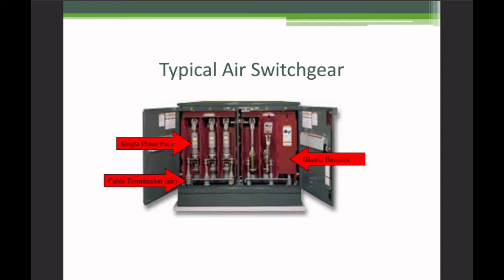As on older vintage equipment, these things are usually made out of asbestos fiberboard. Keep in mind, asbestos fiberboard is completely safe to be around. It's completely safe to operate unless you're asked to start drilling holes in it and generating dust. There's no risk from that asbestos. But if you're ever tasked with tearing one of these down for maintenance or scrapping one out, you might want to speak to your supervisor about what the utility's specific practices and policies are, and if there's any asbestos fiberboard in this particular unit.